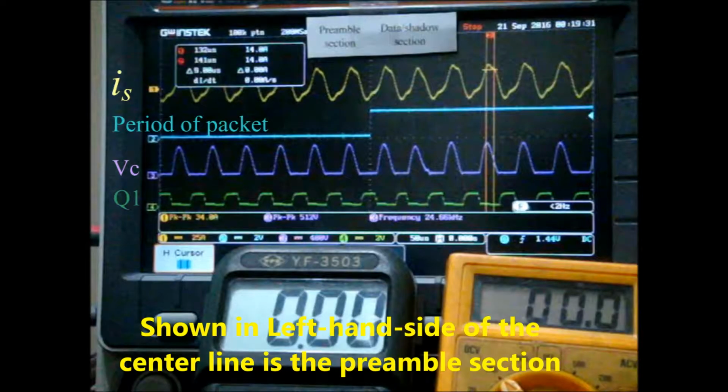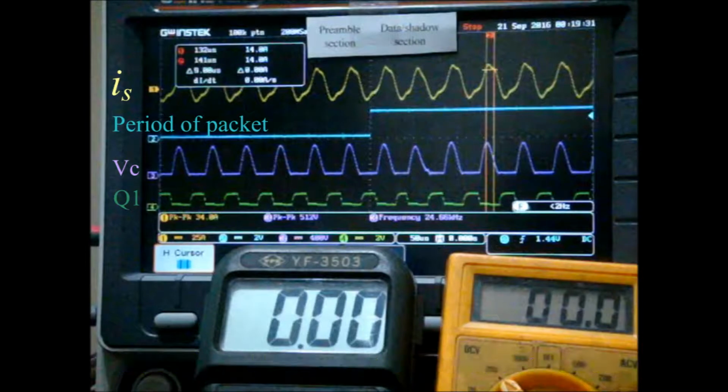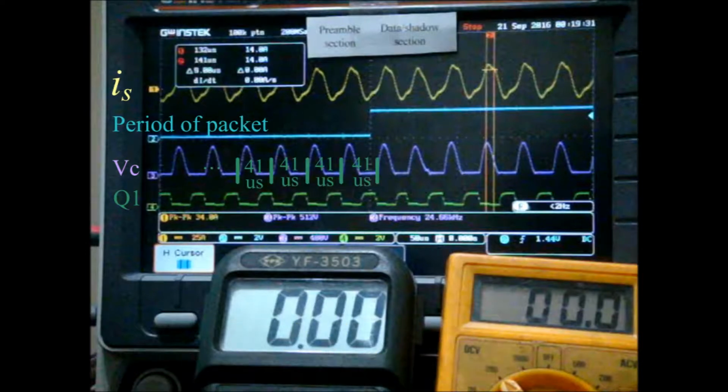Shown on the left-hand side of the center line is the preamble section, and the right-hand side is the data section. In the preamble section, there are data bits. Those are digit 1 without modulation. The time period is 41 microseconds.